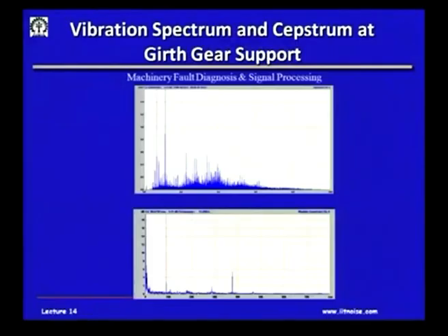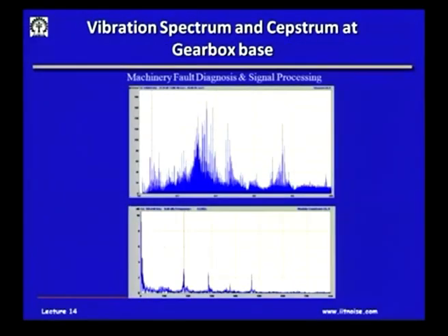Now, if I was to come back to my example here, again look at the vibration spectrum and Cepstrum at the gearbox base. Because of a very poor foundation, you see so many frequencies coming up in the spectrum, and if I asked anyone to find out the frequencies contained in the signal, you will be all scratching your heads, getting lost.